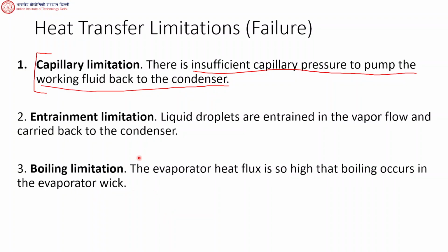And entrainment limitation means liquid droplets are entrained in the vapor flow and carried back to the condenser. So there is a vapor flow, obviously. So the vapor goes this way. But if the vapor picks up a lot of liquid droplets, then that is also a problem.